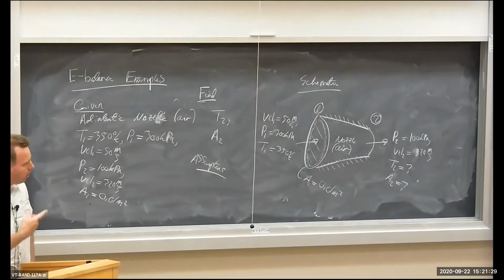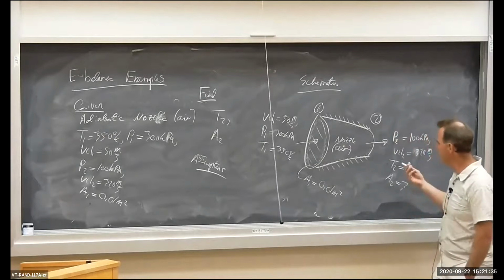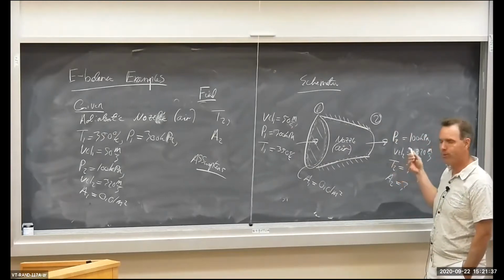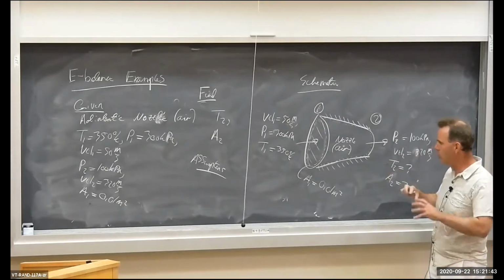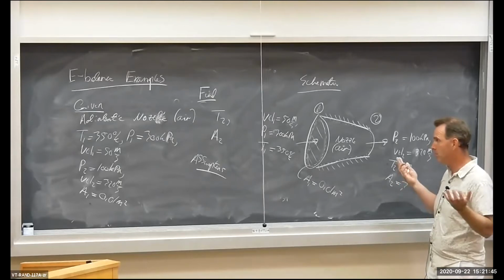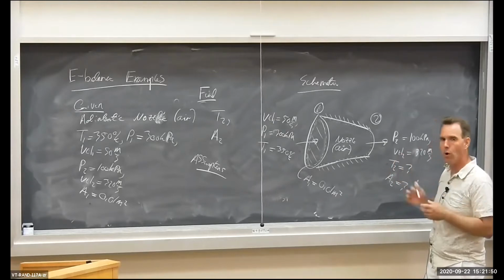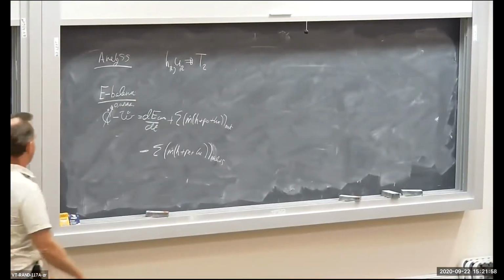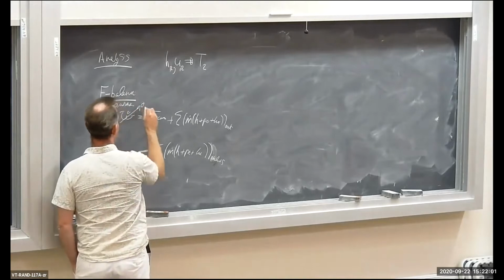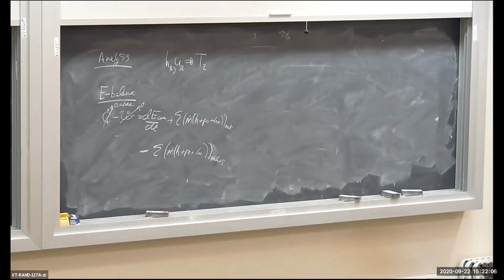Okay? Also, do we see any wires in here or shafts? If there's no wires or shaft, there's no shaft power or no electric power. Also, the nozzle isn't changing shape, presumably. So that means volume isn't changing, so that means no boundary work or power. So the entire work term is equal to 0, apparently. Okay, left-hand side is completely 0 now.